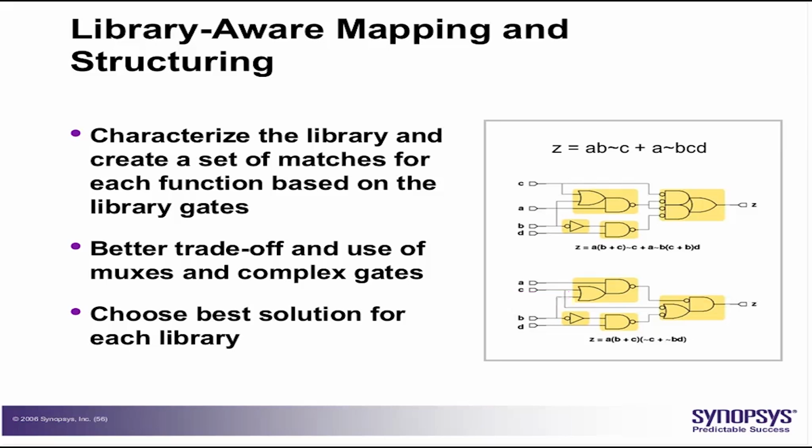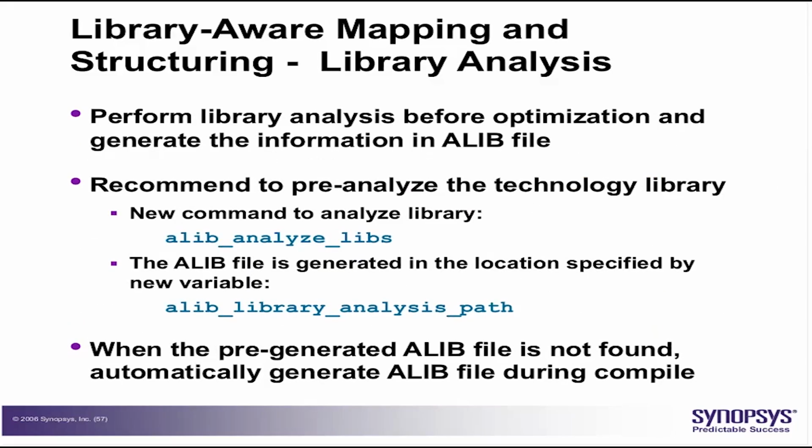Some of these representations would be good for area. Some of them would be good for timing. Please note this is not design dependent. So the library analysis will be performed before optimization, and the information is kept in a file called the alib file.